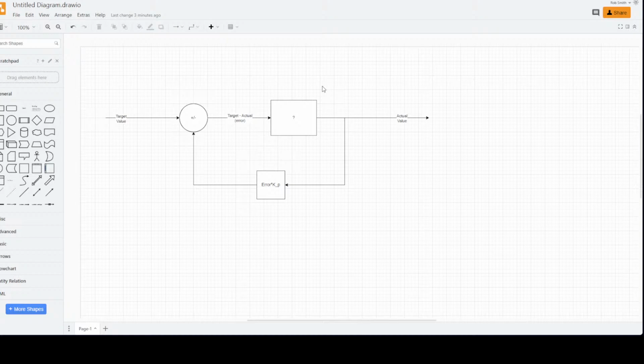The first guy, we're going to call him Mr. P, is flipping out because the distance between you and where you want to be is absolutely massive from his perspective. It's 30 times what he wants it to be, which is, well, 30 million times, because he wants it to be 0. He wants it to be dead on. But the closer you get to 30, the more he calms down. But then you're doing like 31, 32, and it takes him a minute before he starts noticing and caring that you're going faster or slower than 30. His voice is directly proportional to the difference between how fast you're going and how fast he wants you to go.